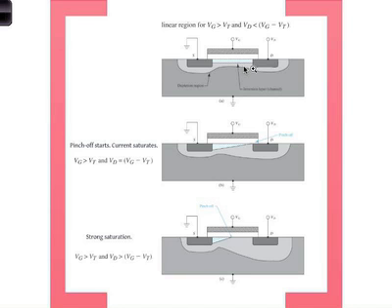Okay? It's a depletion region. But that's not sufficient for carrier flow, right? Because the depletion region means there are no carriers. Current cannot flow. That's the threshold. So you need to do something else. You need to apply a bit more voltage for something else to happen for carriers to exist. Okay? That's the reason for the threshold. We'll come back to that.